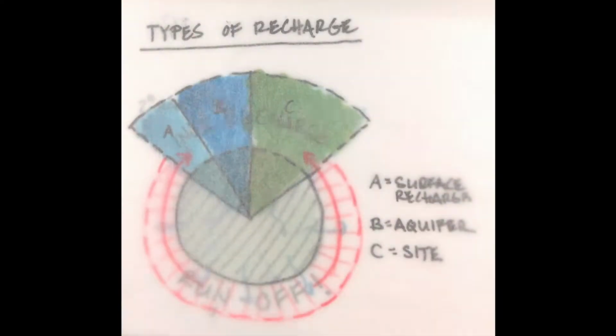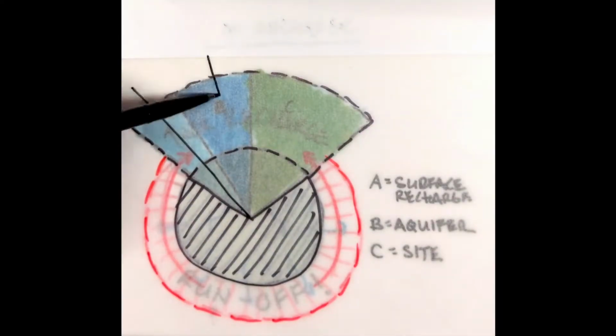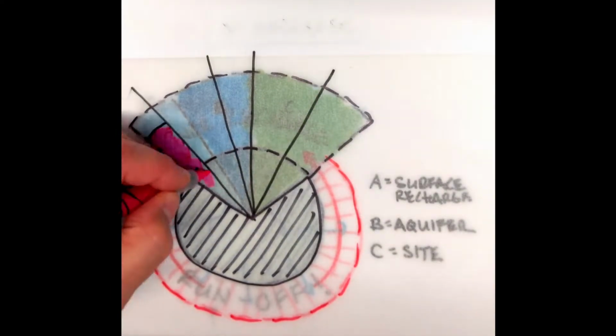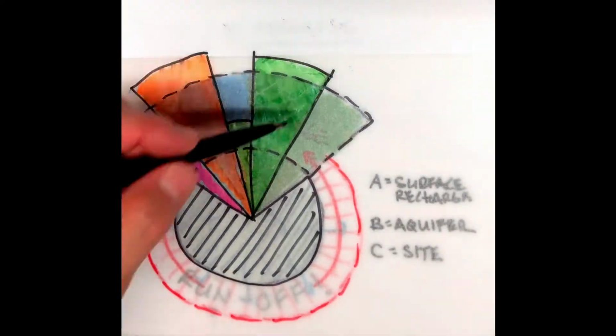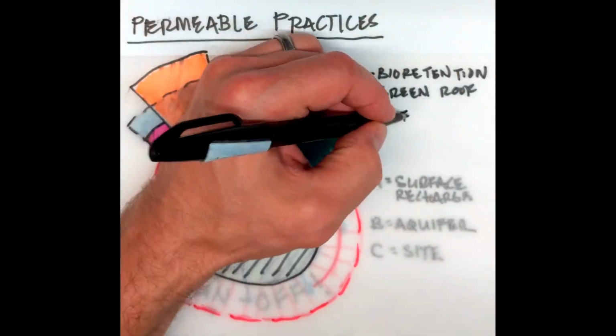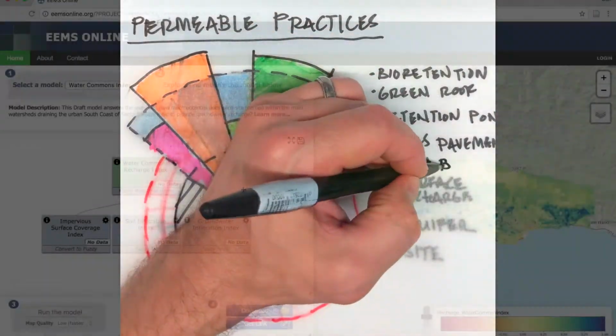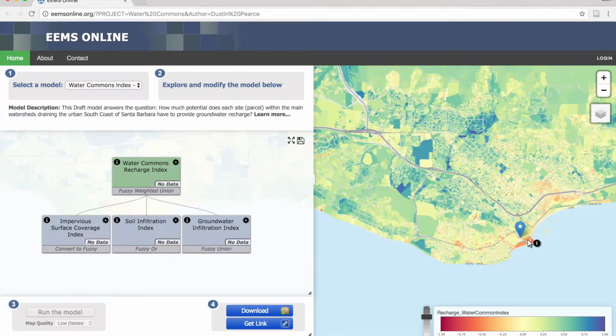The second graph represents our Permeable Practices Index. It is used to track the actual performance of specific permeable practices developed on a site. Options for best practices are primarily based on the infiltration capacity desired, but topographic and regulatory restrictions will likely eliminate some of these options. Once the best options are determined, the tool allows us to analyze cost and environmental issues before making any final decisions.